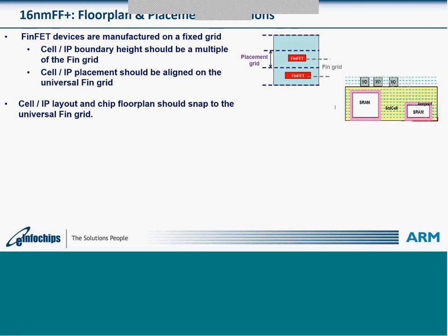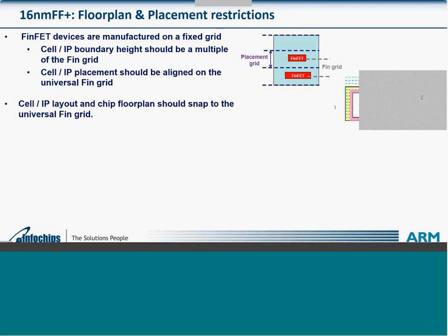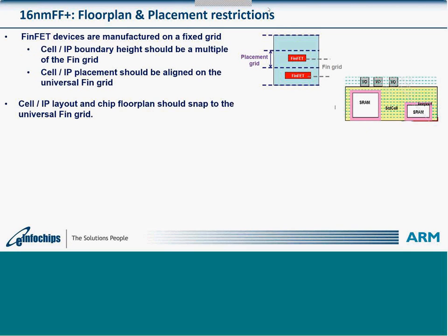So if we just see this image, the grid is defined, but on top of that there is a fin grid. So the fin grid also has to be followed by any of the IP. Basically you have a standard cell, you can have a memory, or you can have SerDes, PLL, anything has to be released on FinFET now.